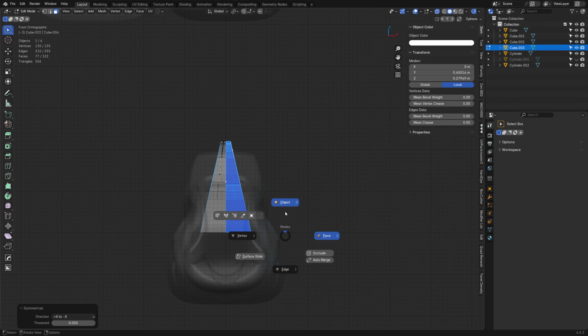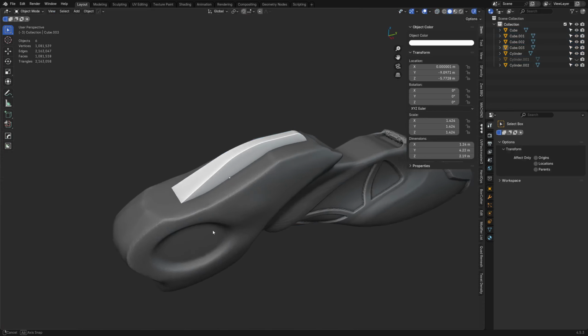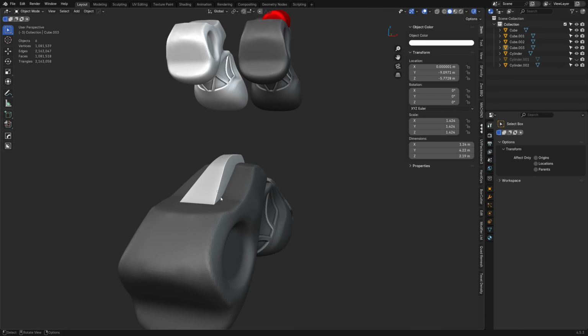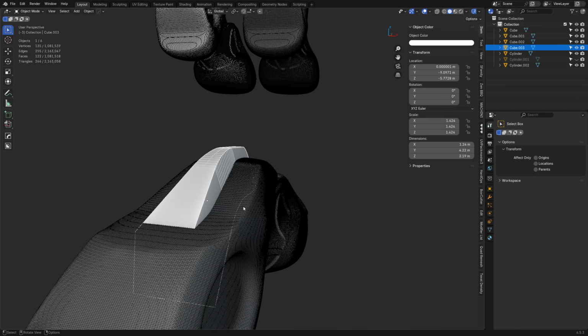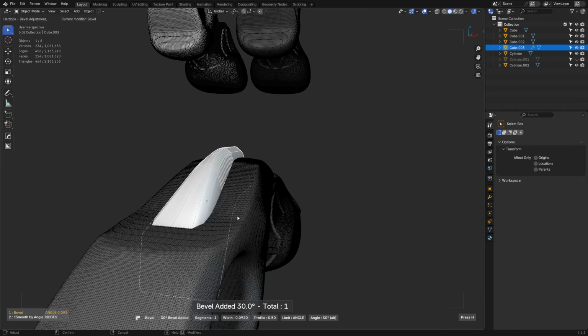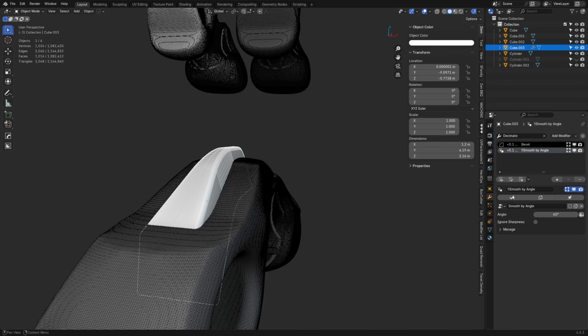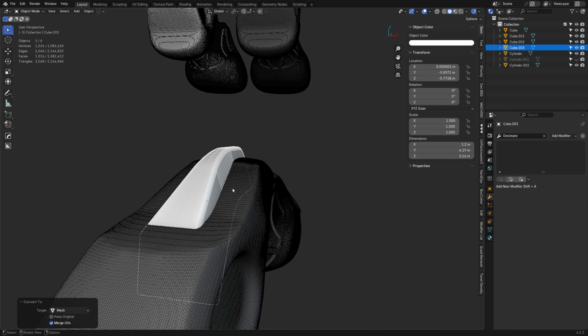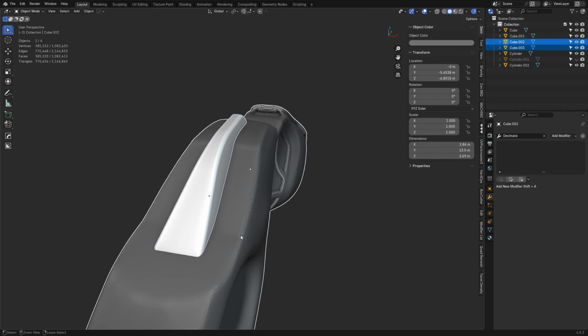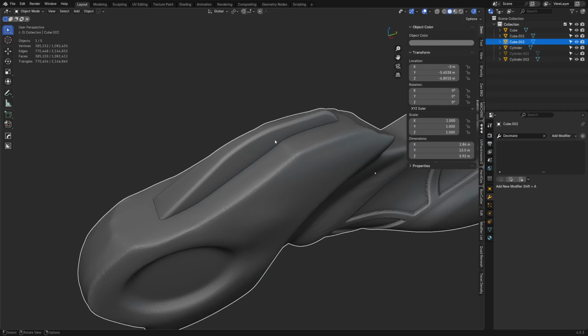So we just got a little taper to the edge there. That's cool, that's kind of a good thing. We could even bevel this with Hard Ops. If you wanted, get a preset bevel going, then just apply it or convert it to a mesh. You're good to go. Join it to this with Control J. Already, it's super clean.